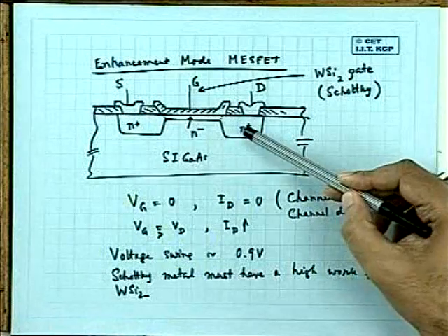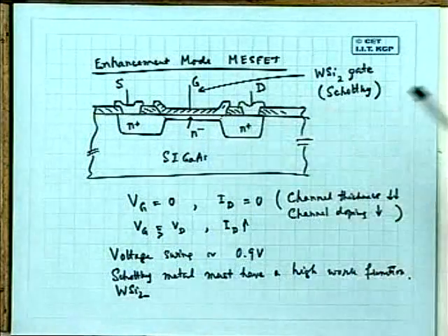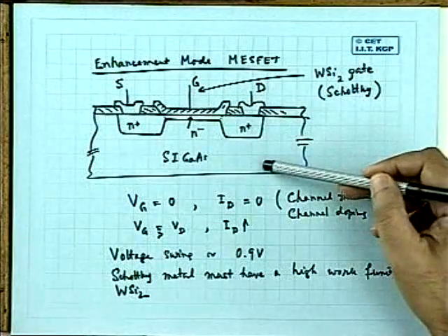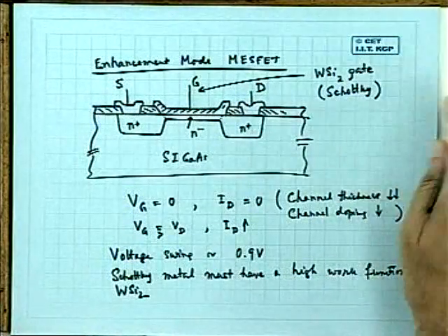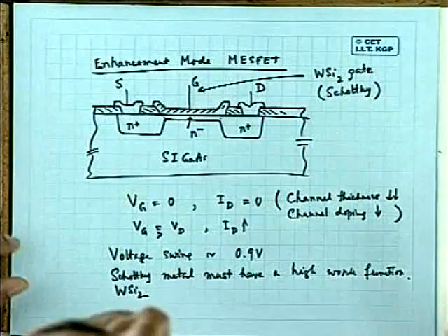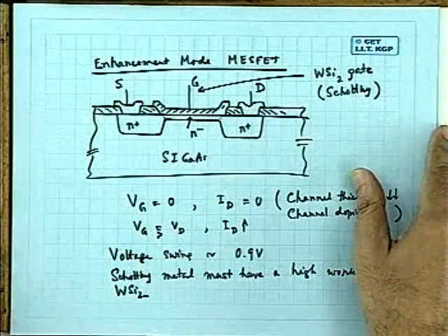And there, the enhancement mode MESFET is the requirement of today, so that you can have a variety of circuits just like MOSFET circuits. You can have dynamic logic also. The only thing is this dynamic logic will work only at a very high frequency. Why? A dynamic logic using MESFET technology normally will work at higher clocking rates, higher clock frequencies than those using silicon MOSFETs.